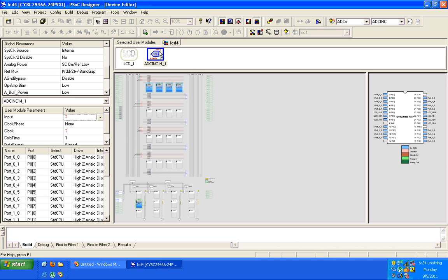After placing the module, we have to set the input and output ports. This is configurable. Then we need to place the inputs and outputs. How? Simply select user module parameters. Here for input, give some input. For example, this is your choice. I am giving the ACB00 block, and the clock is VC2. Always select unsigned format. Now you can see the difference here. So this is about the interconnect view.